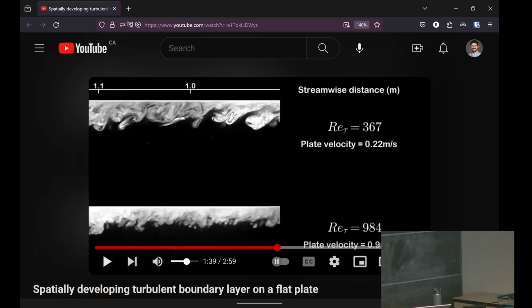Yes, please. In the Couette flow, with moving opposite boundaries. It was Couette flow. So Couette flow is what we studied last lecture, and that's a very specific case of fluid motion. This is much more general. This is usually what happens. In order to actually produce that linear velocity profile in a real flow, your plate has to be in a very thin gap, and you can't tow it too fast or else you'll induce this turbulence. So Couette flow is basically used as a very convenient type of flow to study shear stress and viscosity in a fluid. But most of the time you can't assume you have Couette flow.